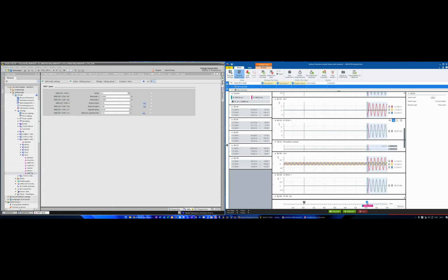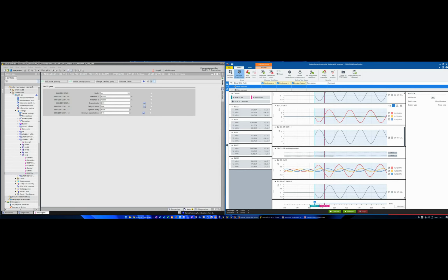So for example, I put the two signals here together. I will zoom in and take here. For example, you can see that my current in my bay CX starts here, but my circuit breaker contact says that it is closed just here. What is the interval time that you have between here? Just 50 milliseconds. This is very common to happen, and this is not a big time. I can say that it is a very small time, and it happens when you close in the fault.